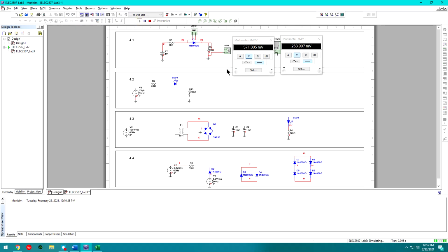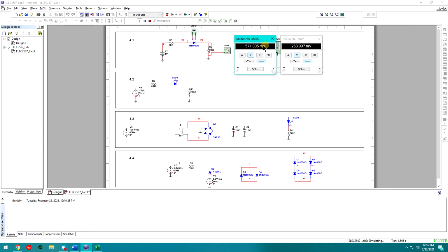So go ahead, and we'll see that we have a slight voltage drop across the diode. This is like the minimum turn-on voltage, basically. And we see that we actually have a slight voltage drop across the load, and the rest of the voltage that's not getting dropped across here, the total of the 1 volt, is actually getting dropped across the source here, which is 50 ohms, which is quite comparable to the resistance of this node here, right? So we know that we're not going to be dropping much more across this whole branch than we are across here. That'll really become apparent as we increase our voltage here.